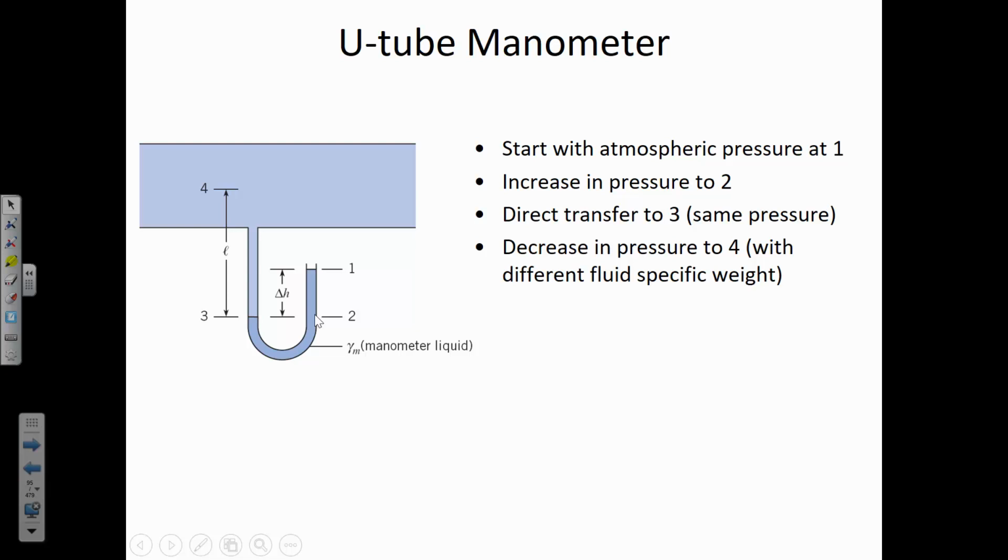Equilibrium? Same elevation, same liquid. Now, I want to be sure that everybody gets this. Same elevation doesn't mean same pressure always. For instance, here at 1, the pressure here and across from that is not the same. It's only the same pressure if between them, you're going through the same fluid.